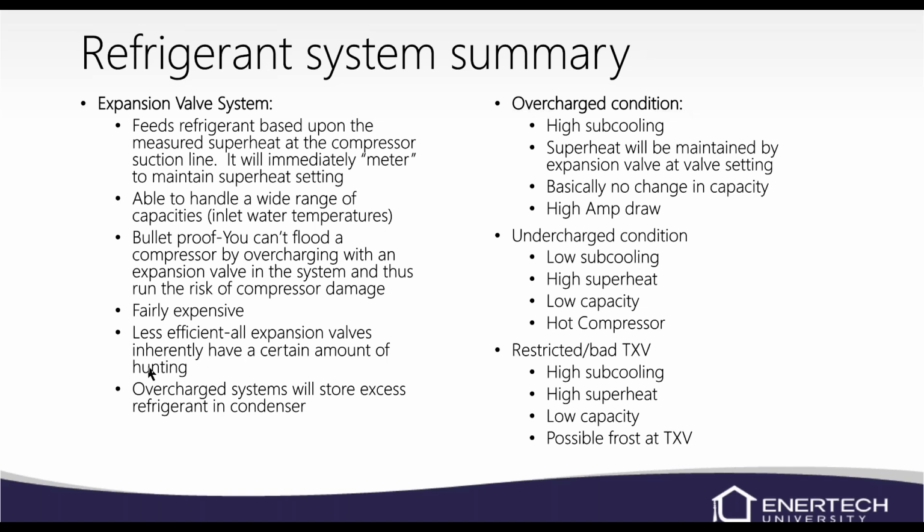All expansion valves will have a little bit of hunting in them, so you might see a little bit of jumping around on your pressures, but you shouldn't see a whole lot. And again, we're going to store that excess refrigerant in your condenser. So when we get into overcharge conditions, we're going to have high subcooling.